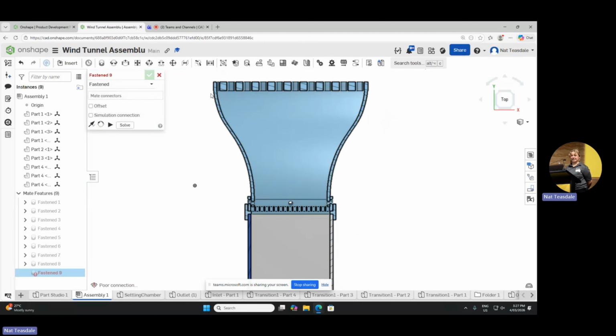If, for example, this was to be shorter and we would have an S shape, which is more like this, the angle here would make it too strong, and for the same reason, you would end up creating areas where airflow is getting constrained and you are losing efficiency, essentially. That is why when we do CFD simulations or some sort of testing, there are things that we look for when we develop any sort of airflow design or airflow system and make sure we design around it.